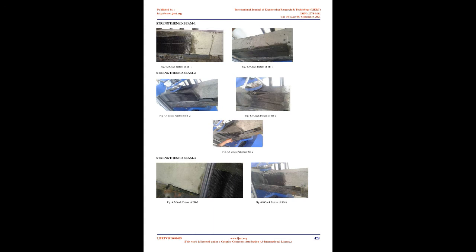Form work. Fresh concrete, being plastic in nature, requires good form work to mold it to the required shape and size. So the form work should be rigid and strong to hold the weight of wet concrete without bulging anywhere. The joints of the form work are sealed to avoid leakage of cement slurry. Mobile oil was then applied to the inner faces of form work. The reinforcement cage was then lowered and placed carefully in position inside the form work with a cover of 20 mm on sides and bottom by placing concrete cover blocks.